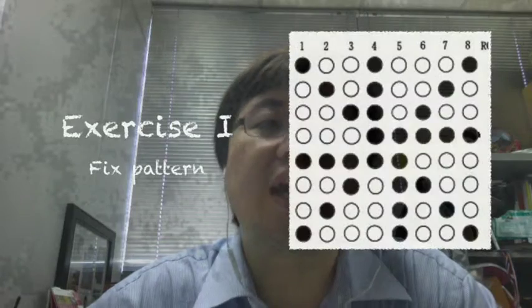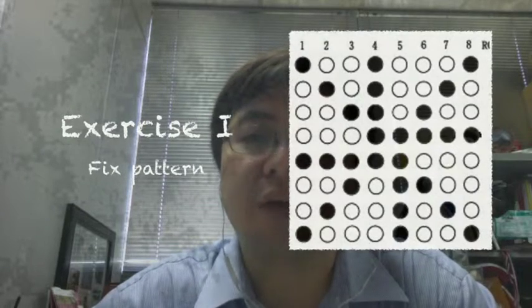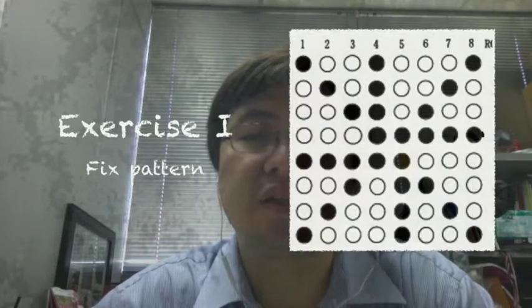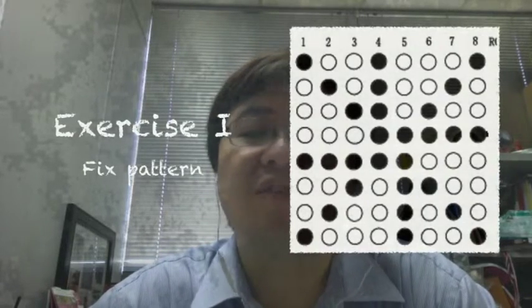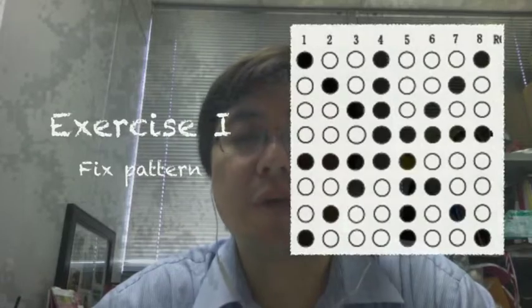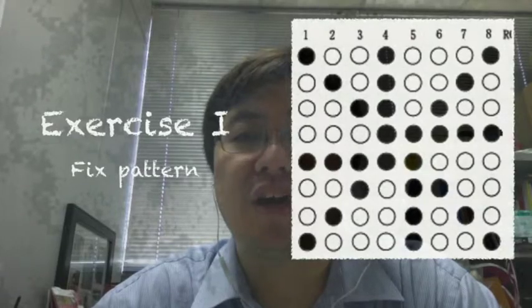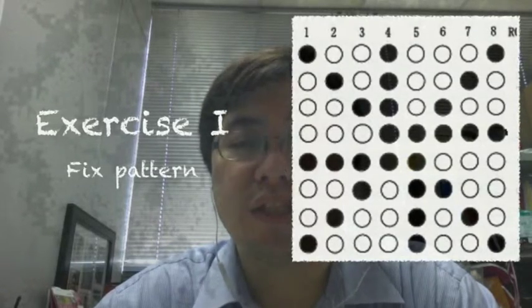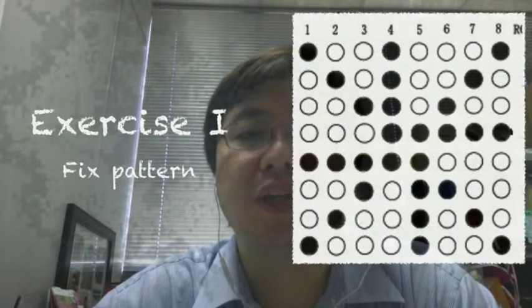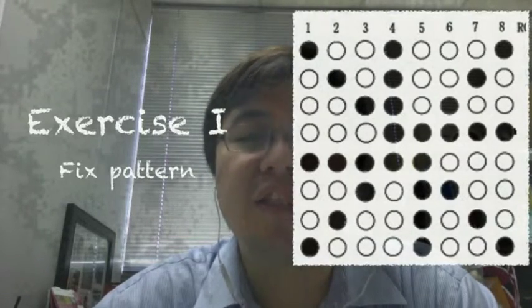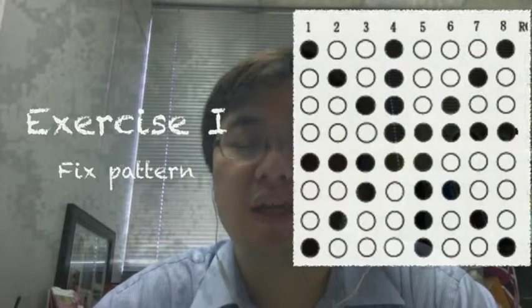With the LED matrix, you're gonna see altogether 8x8, or 64 LEDs. You would guess that if we have to drive that many LEDs, maybe we need so many wires or so many lines. For example, if we have 64 LEDs, technically speaking, you would need about 65 lines, including 64 for each one and one common ground or common voltage, depending on how you connect your circuit.